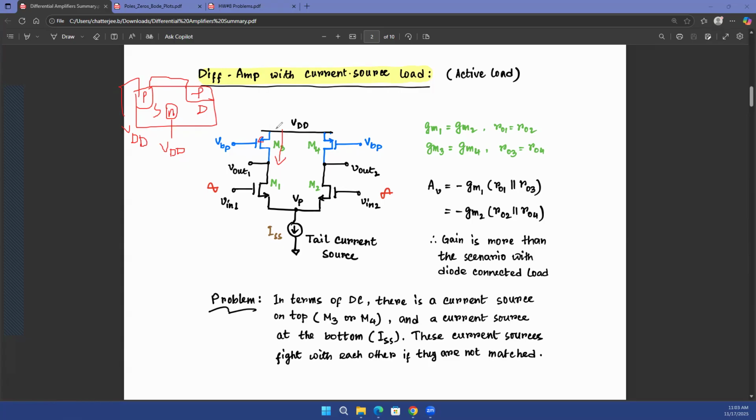That is also a reason why in any circuit, the top portion is designed using PMOS and the bottom portion is designed using NMOS. Your output is generally in the middle, but you are able to connect the source and the body of the PMOS to VDD, whereas the source and the body of the NMOS to ground, keeping those leakage currents at a minimum.